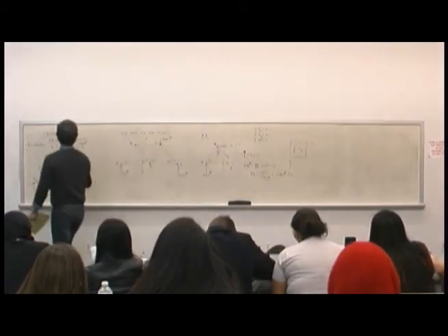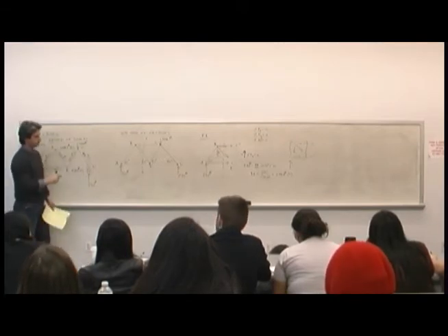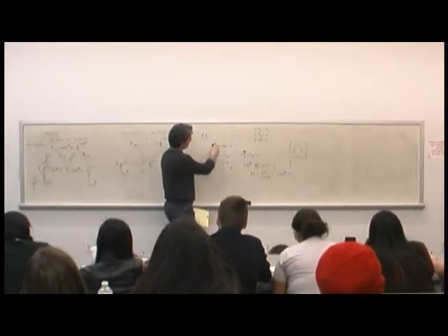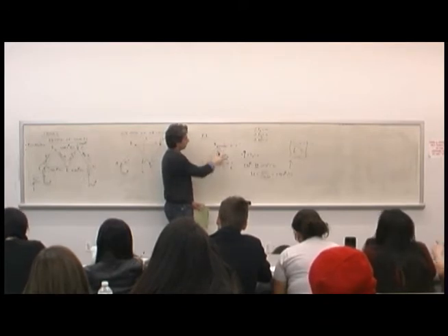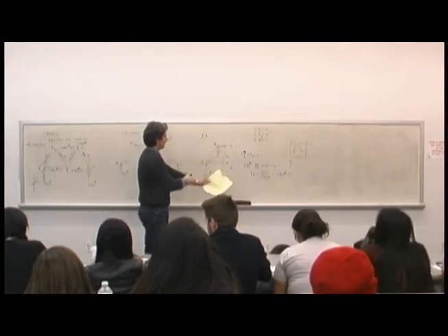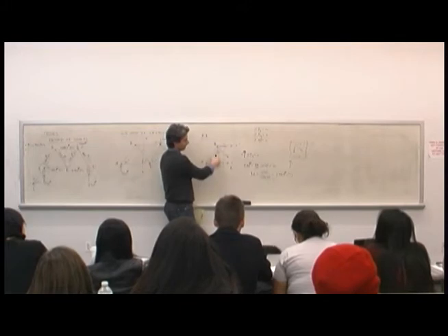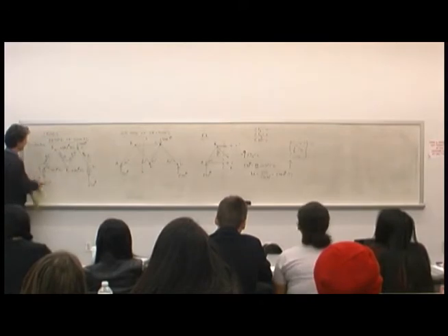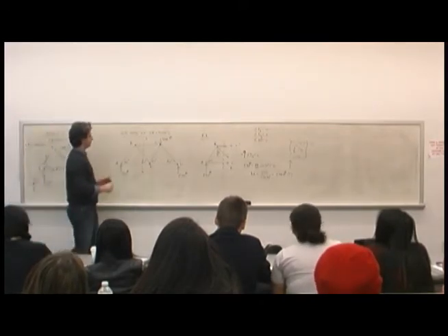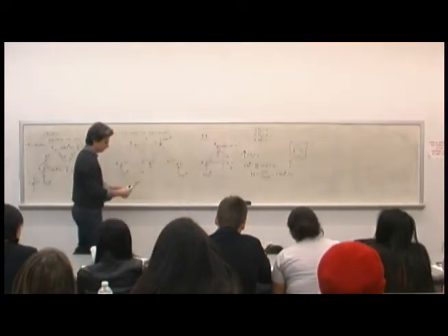And that's what we end up with using method of joints doing the same thing, right? So I did it in a different manner, but I really did the same thing. All I did is I just balanced the system, right? So now you have a new way of thinking of the structure. You can quickly isolate something, find that internal force, and quickly zoom in on it. In the other case, we had to go point to point to point, and travel through the truss. In this method, I can isolate and find one particular member if that's what I'm looking for.